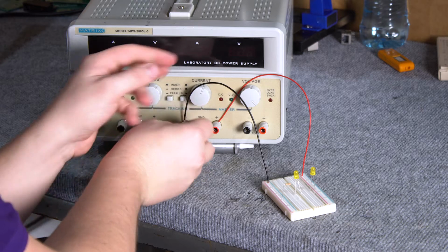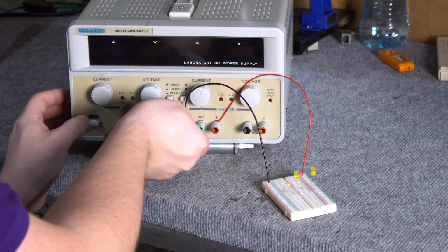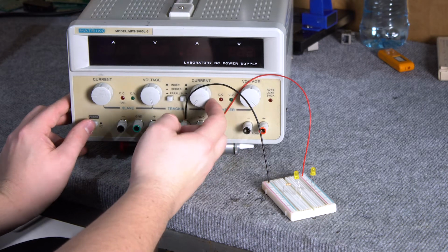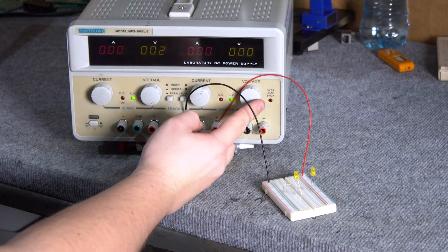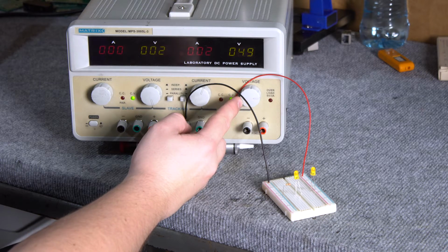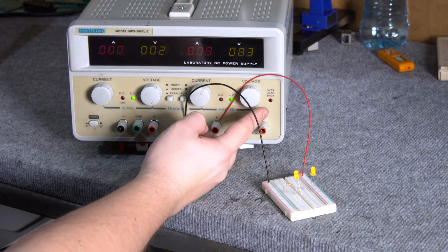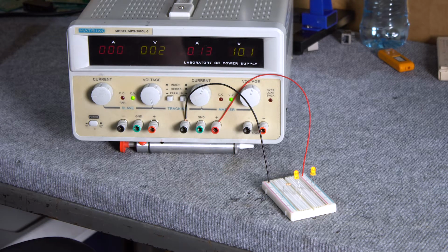For the infrared diode, 1.2 volts, for the red diode, 1.4 volts, and for the white diodes, it is around 3.2 volts. Sometimes we do not know, and in this case we can set the power supply to 10 volts voltage and 20 milliamperes current limit. However, already at 2 volts, the diode would start to take over 20 milliamperes, so the power supply will switch to the current stabilization mode and it will work in its safe range.